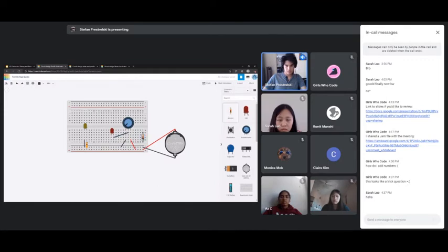Actually, I'm going to add just a resistor there so I don't blow up the LED. Rotate you around. Put this guy here. This wire can go to the LED here. Put the LED there, then this goes to ground. If I start the simulation, I can adjust the potentiometer and turn up the brightness of this LED.